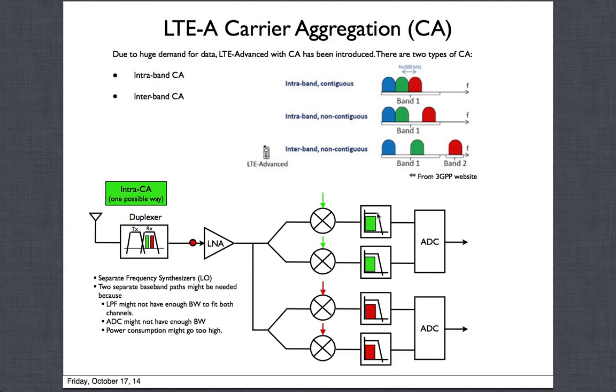Just by increasing the bandwidth of the low pass filter and burning more power in this filter might be okay for the filter, and it might still be able to deal with the interference and all that. But when we go to the ADC, widening the band of the ADC and still saying we need good resolution is not a simple, straightforward linear scaling in an ADC. So all these constraints could put a lot of pressure in terms of the reality, whether you can actually design such things and how high the power would be.